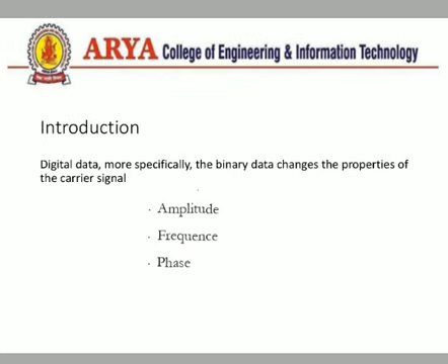Amplitude shift keying is a type of digital modulation technique. Further, digital modulation technique can be classified as coherent and non-coherent technique, depending on whether the receiver is equipped with a phase memory circuit or not. In the case of digital modulation technique, the digital data, that is the binary data, changes the property of the carrier signal. What will be the property? Property will be namely amplitude, frequency and phase.